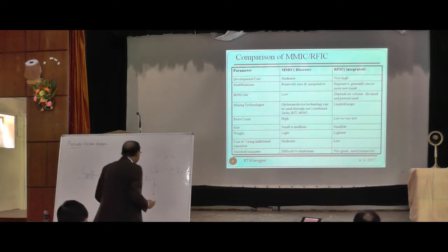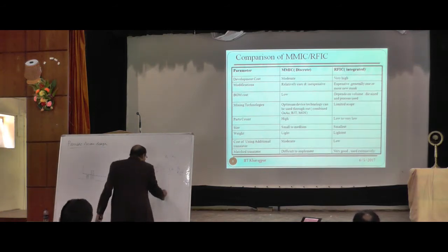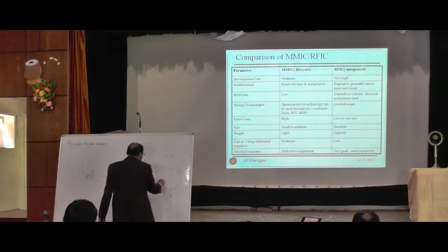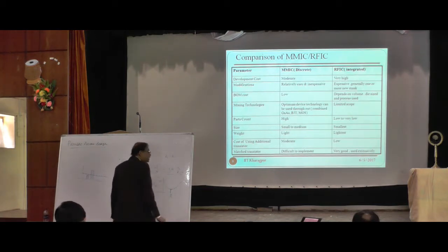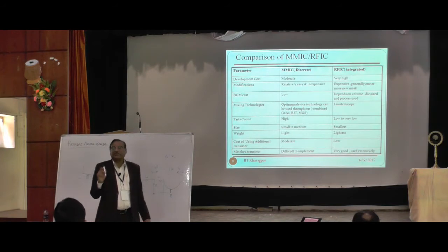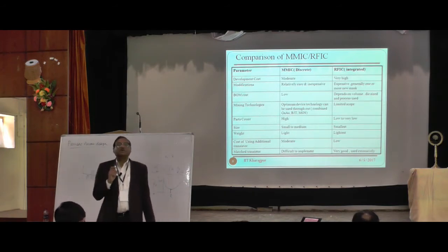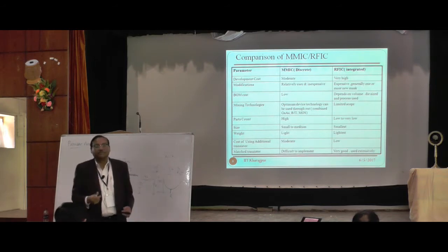In that case, I will try some kind of impedance matching like that. I know this is the point where, on this axis the R value, and this is say noise factor or gain. So at some optimal value of R, I will get the minimum noise figure and that point's maximum gain.